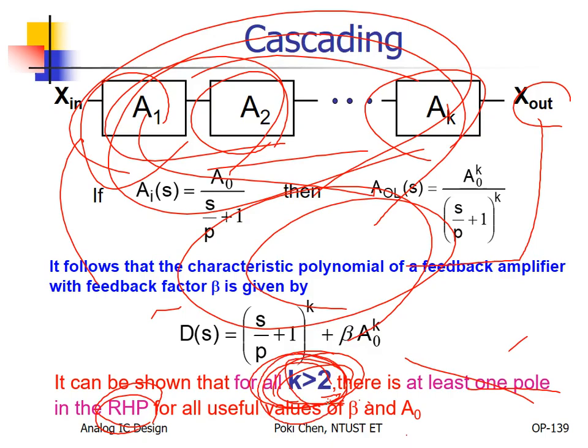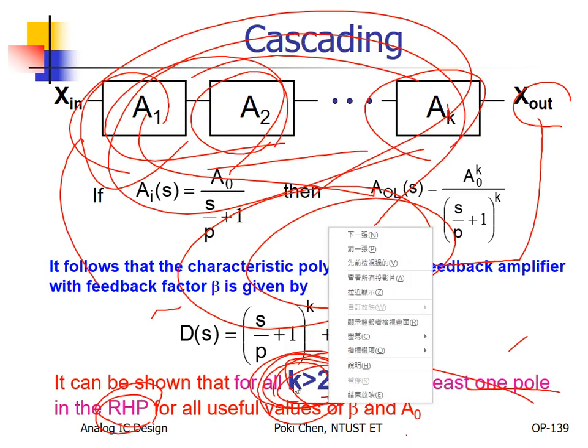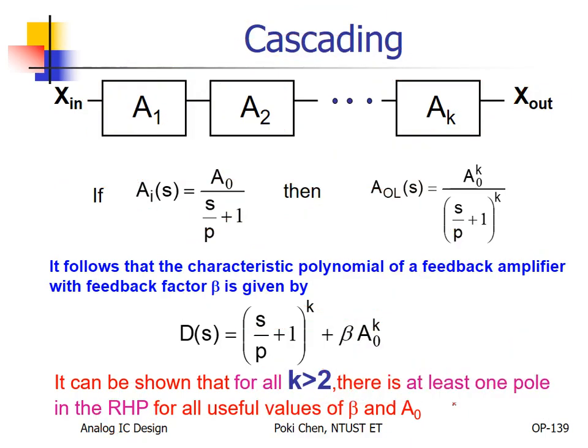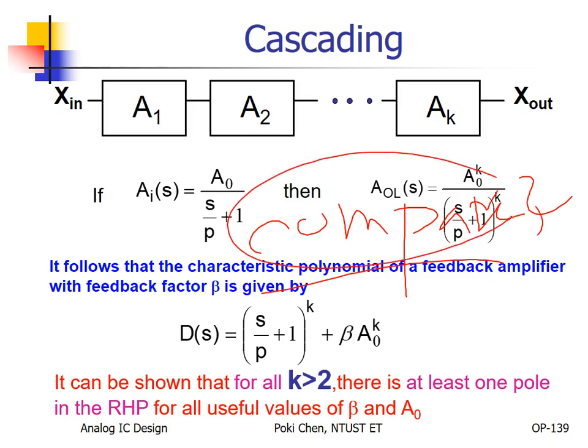Okay? Maybe you will be curious. What kind of open loop application for such a high gain amplifier? Comparator. Voltage comparator. Okay? For ADC, you need to compare your input voltage to see if it is higher than this quantization level or that quantization level. Above it or lower it, you need the comparator.